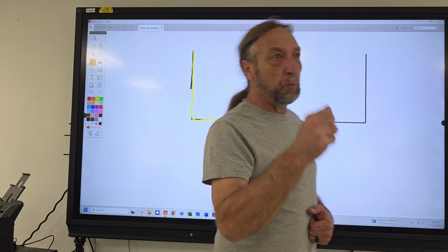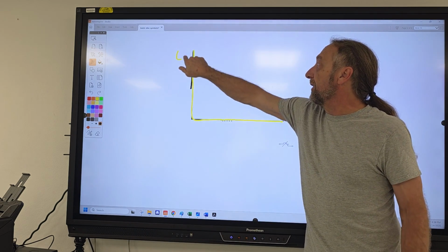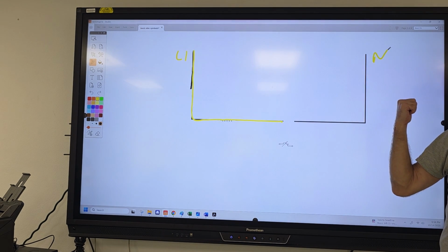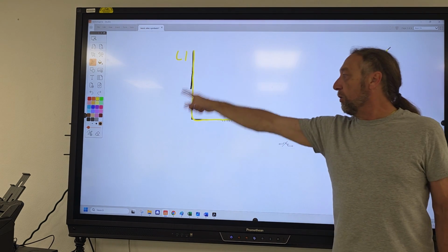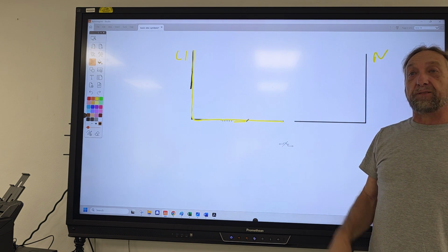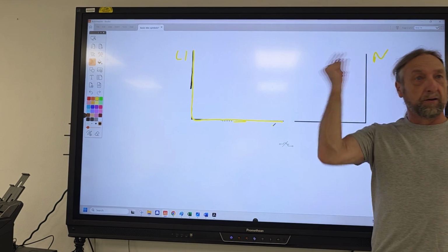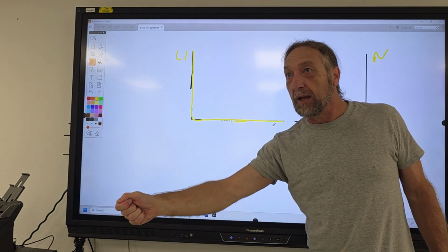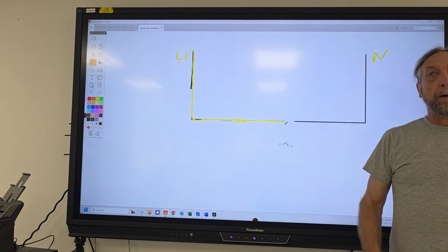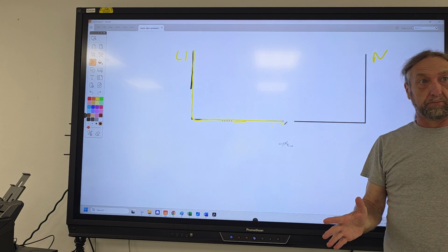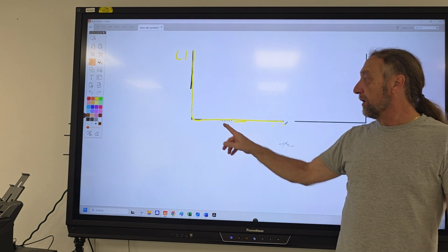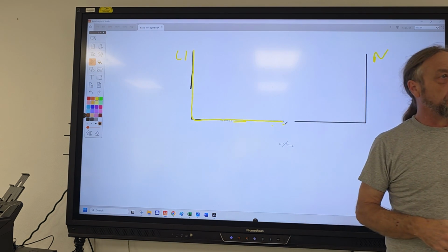So as soon as you plug it in, electricity's over here, line one, neutral's over here. Electricity wants to go in line one, come out neutral. It's going to come in here and will flow through the element till it gets to here. You know how fast it takes to get from here to here? Like that. As you're plugging it in, before you even let go of the plug, the electricity already made it over to here. But then it stopped. Unless the current is continuing to flow, there is no heat being generated by the element.